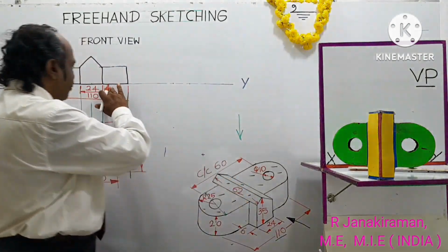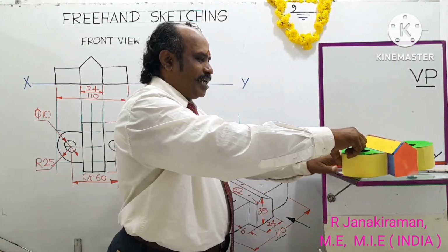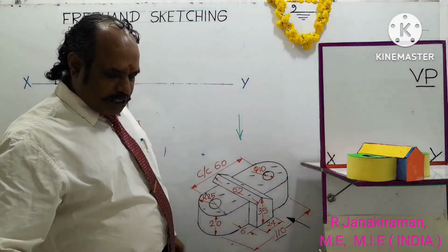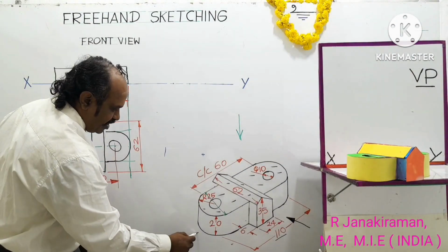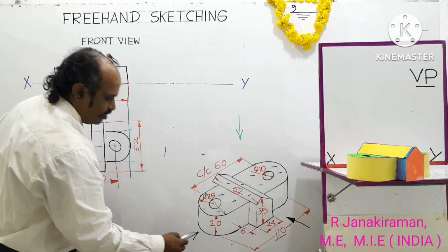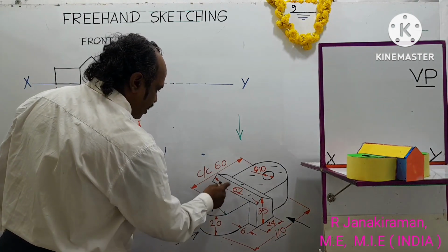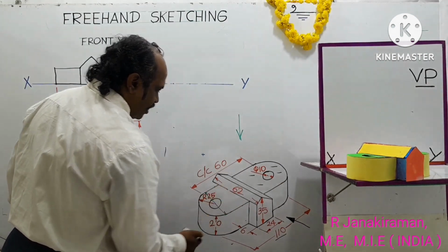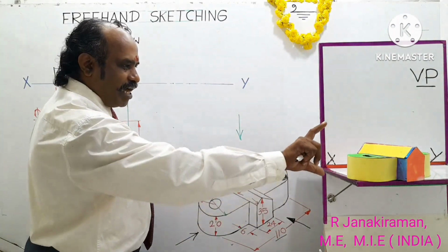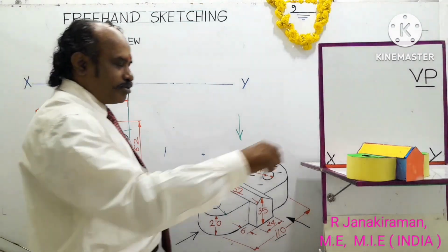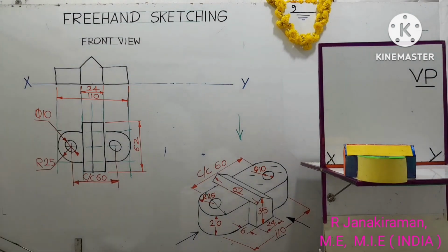It shall be drawn on the right side of the front view, following the first angle projection principle. Earlier the object was placed like this. So now for this arrowed direction, this is the left side. Viewing in this direction, the observer can see the portions which have to be identified. You can see the base breadth of the object and the height of the object. So I turn the object so that you can see it in the camera. The view obtained is called the left side view.